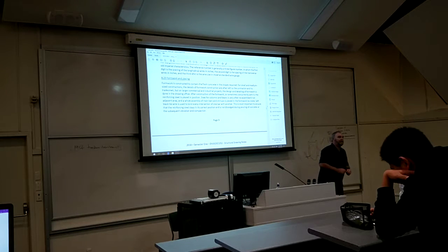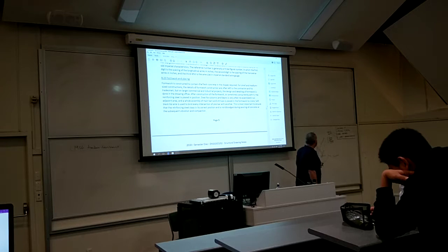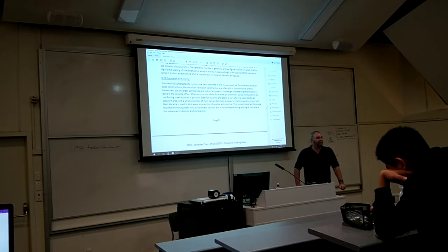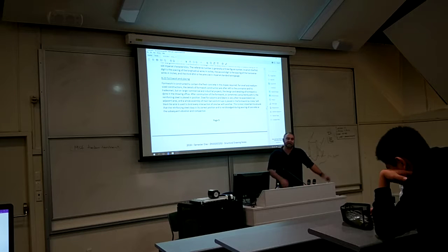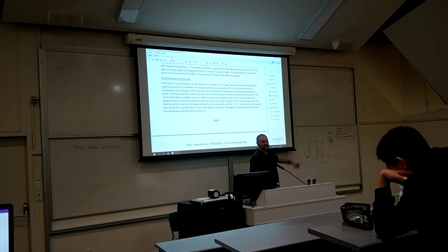So if you're asked to do quantities in terms of formwork, you would just measure these pieces here, the flat face, and of course the two ends of the retaining wall. If someone was talking about the false work that you might require, they're talking about that, and if they're talking about the boxing overall, you need to calculate this plus the false work. Alright? So if you understand that, you should be able to answer a couple of multi-choice questions that I have lined up on that.